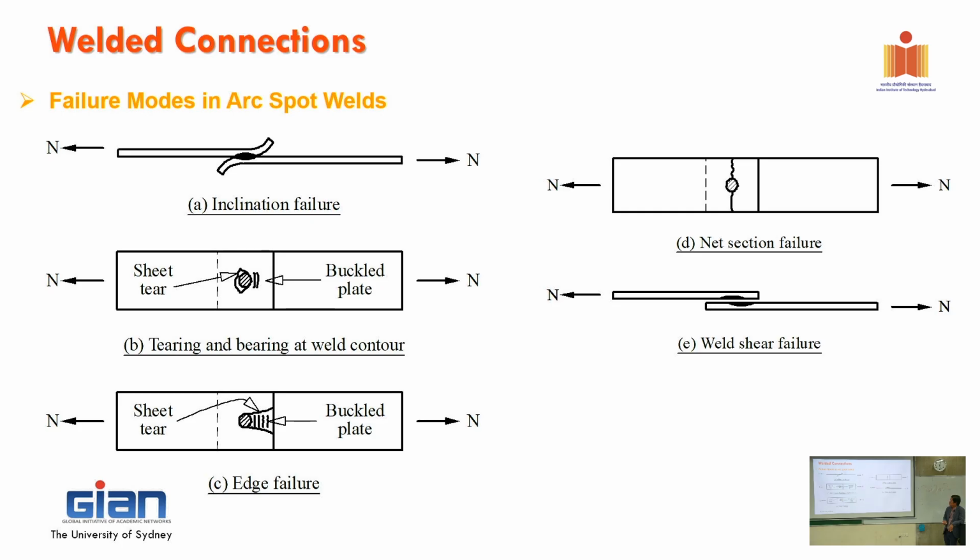Right, and the other problem that you can see here, when you put a weld and you pull it down, there's a lot of curling problem. And what you have here is buckle plate. When you make the weld and you pull it, this plate in that area is under bearing and compression, all right?